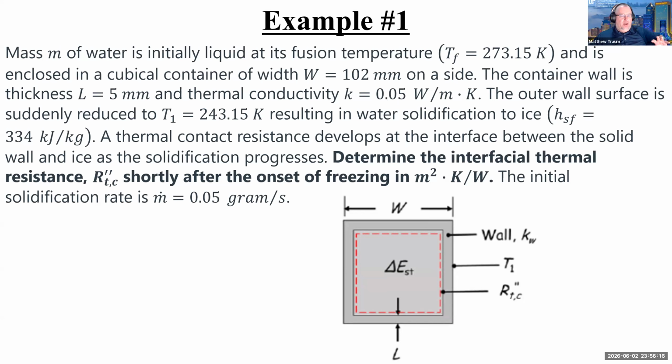And when I was originally given this problem, these are textbook problems, it was all in Celsius, and I am doing the work of converting it to Kelvin for you, just so that you don't get confused. But always, always, always, if you have temperatures in Celsius in the world of heat transfer, please convert them to Kelvin so that you don't end up multiplying or dividing by degrees Celsius and getting yourself messed up, right? I'll try to do it for you, but out in the real world, everything is in Celsius. So just remember to convert everything to Kelvin so you don't run into mathematical hardship from not using absolute temperatures.